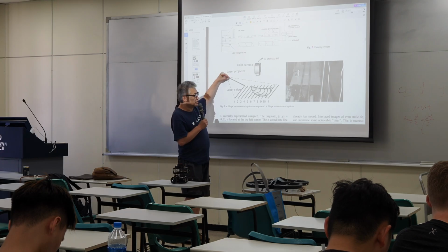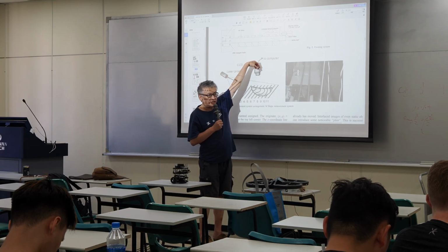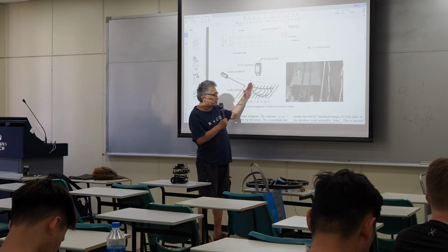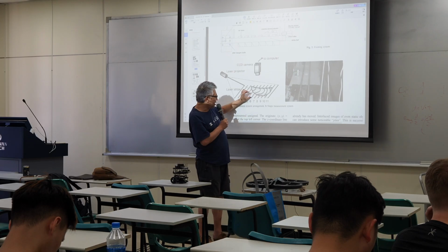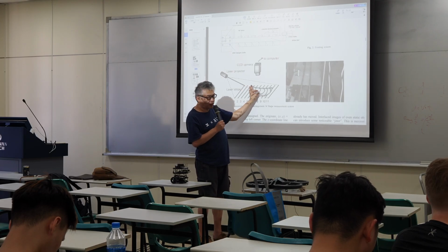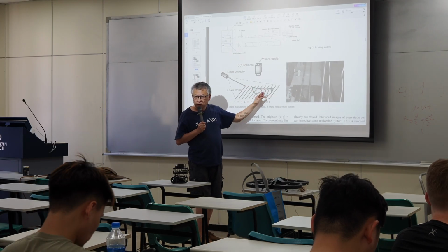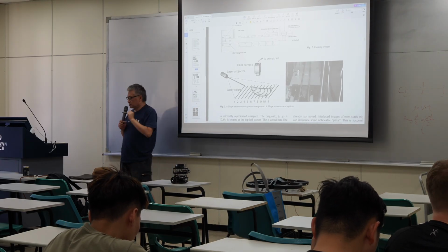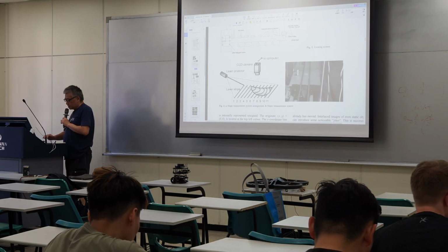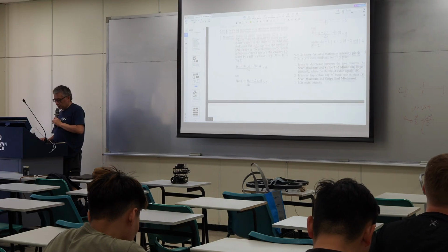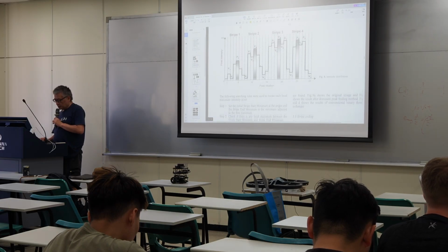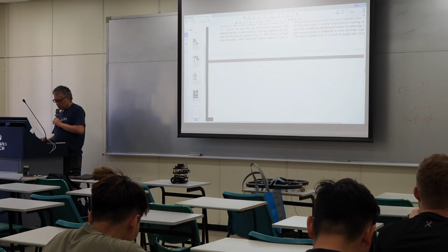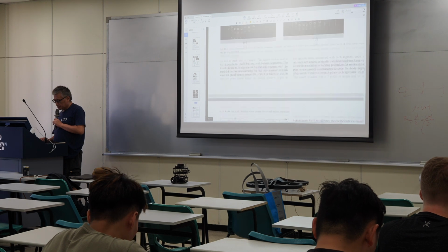So one regular camera and one structured light. You project the stripes in there, and the shift of each stripe is proportional to the depth. To the depth. So simply to say, this is the principle.